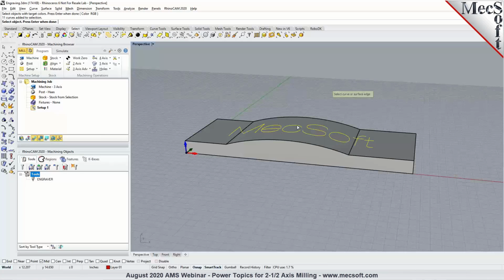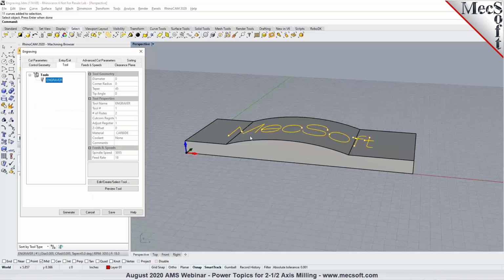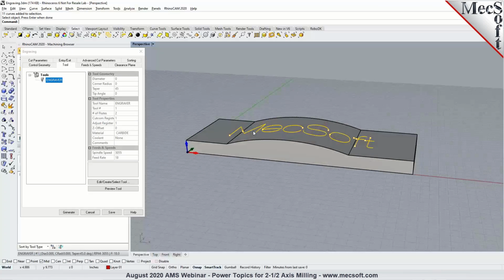Now you may notice that we have a single stroke font. I'm going to show you how we can avail that single stroke font. We've developed a single line font, and you can download and install it onto your computer, and you can define text using single stroke fonts and use the project command in Rhino to project those text onto the surface.